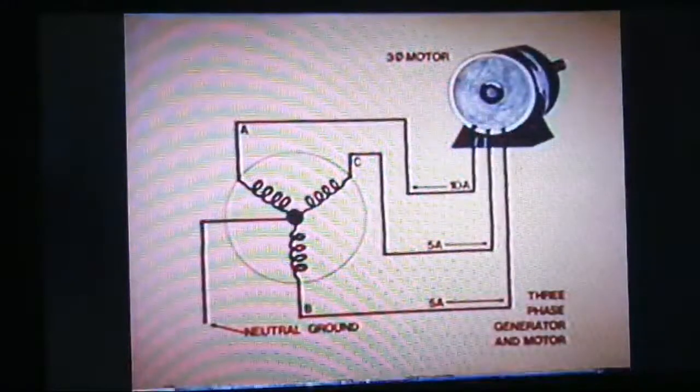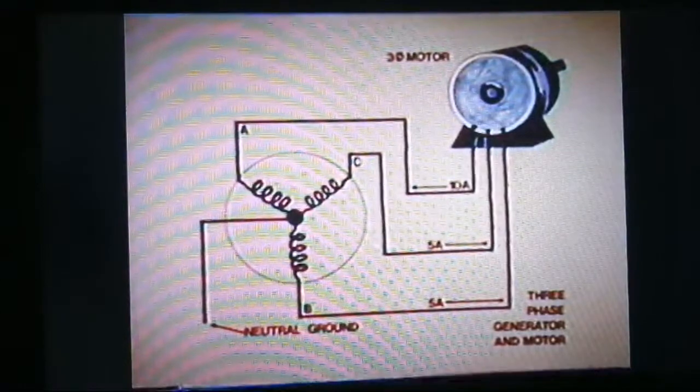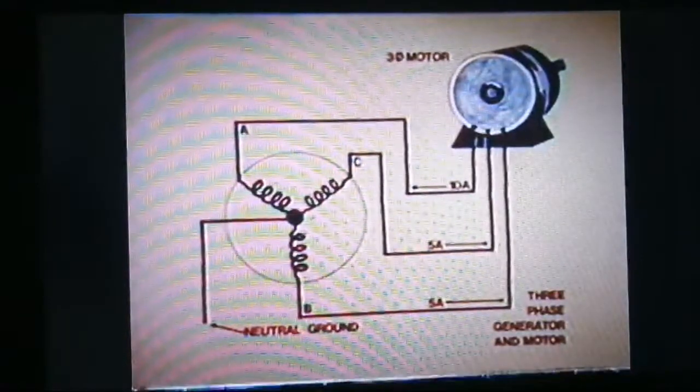A three-phase electrical system can carry power from generator to load with only three wires. Much more power, smoother power than with a single-phase generator, which would require two wires anyway. A ground wire using the earth itself often serves as our common, and earth grounds will be discussed in a later lesson. Well, the principles of AC generators that you have just learned won't change. The way engineers apply these principles and the specific equipment used are the subjects of subsequent lessons.